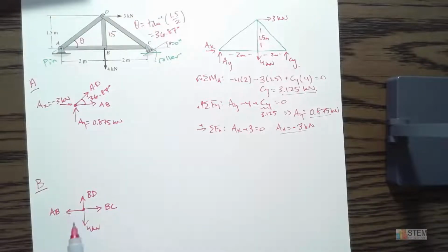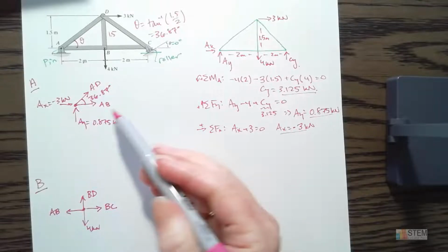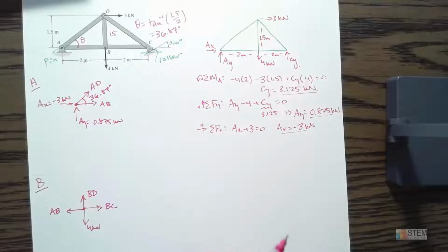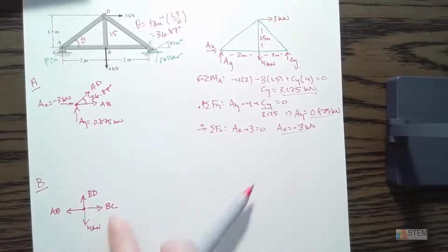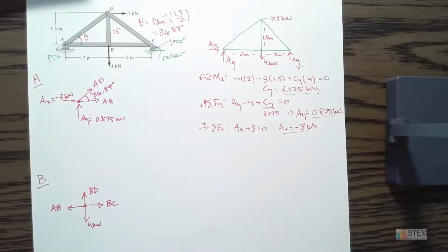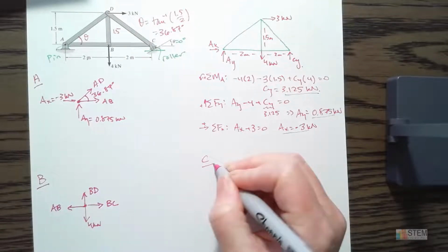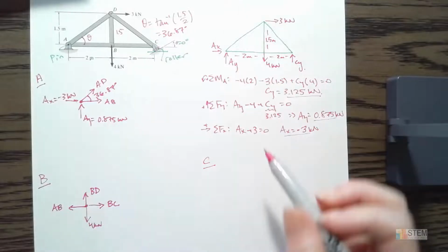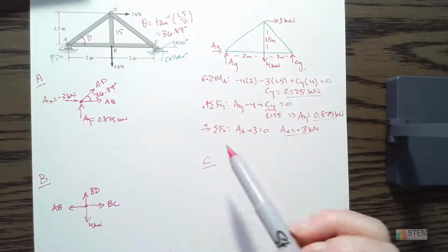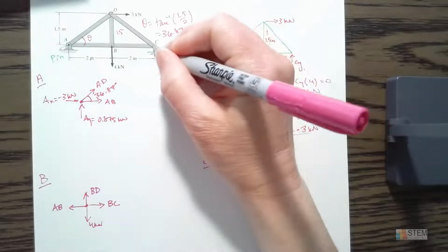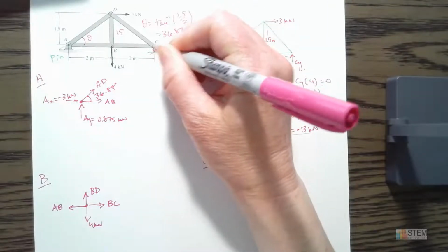Now notice in doing that, this one and this one are opposite, which is what we need, right? Because we've got that equal and opposite reaction. So that checks out, looks good. Okay, so this one we've got 3 unknowns. So let's keep going. Let's do C next. I'll do C over here. So C is right here. And remember we had an angle of 0 degrees, so this roller is really like right on this surface here.